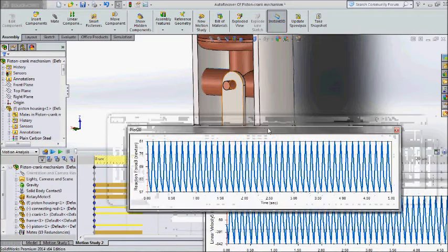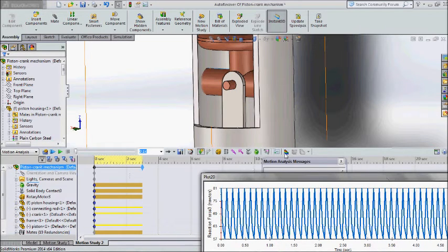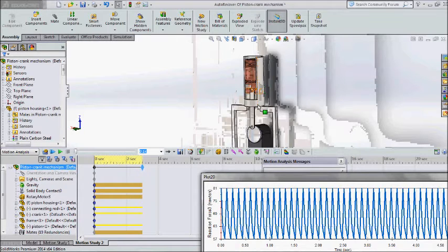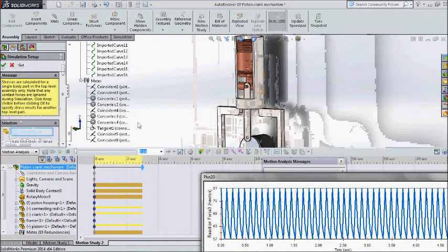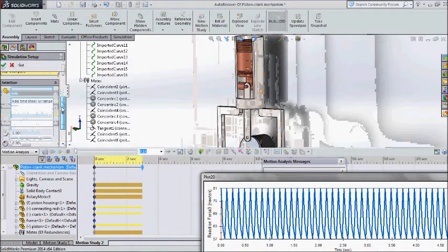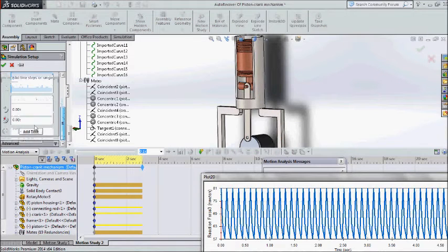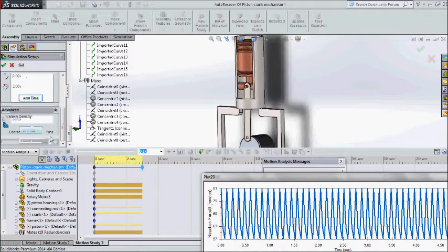And then we can move on to exporting a particular component for stress simulation. We can do that by clicking this button here, and then it will tell us to add a time step or time range for investigation. We can take 2 seconds, 0 to 2 seconds. We add such a time, and we also have the ability to change our mesh density.